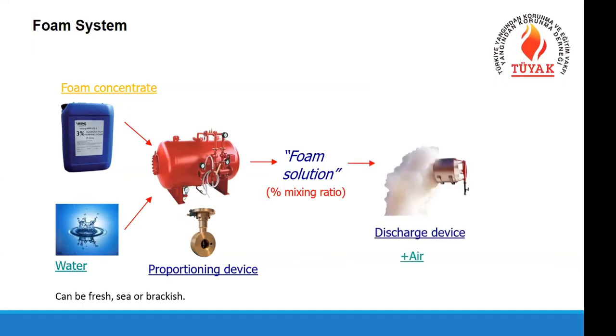These discharge devices are special equipment that picks up the foam solution and combines it with air, and it finalizes with the foam. Not a solution anymore. The solution is water and concentrate, and when you mix it with air at the end with the discharge device, it becomes foam in final shape. So it becomes bubbles on the discharge device.